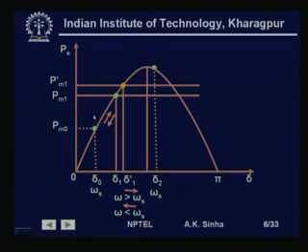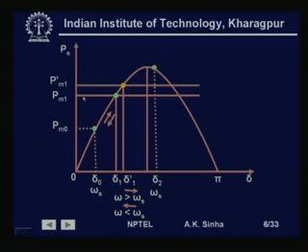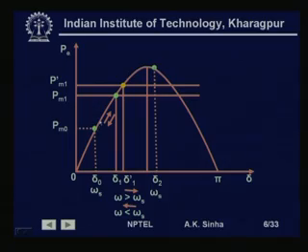Because of this excess mechanical input to the system, there is going to be acceleration, because now we have excess input and less output. Because of this, the rotor of the turbine generator system is going to accelerate. If it accelerates, it will start moving on this line where we have the P delta characteristics, that is the electrical output characteristics of the machine.